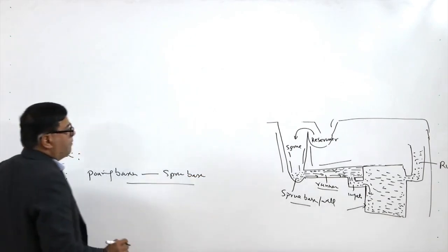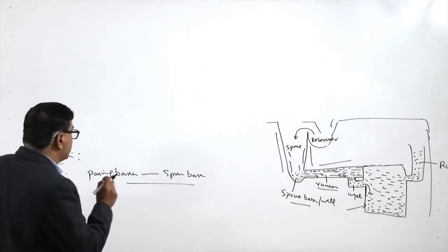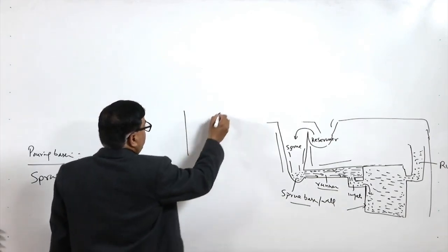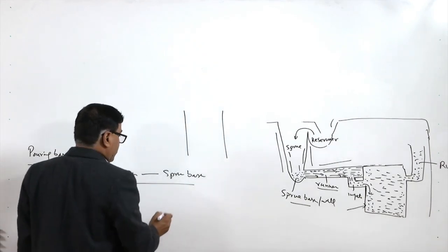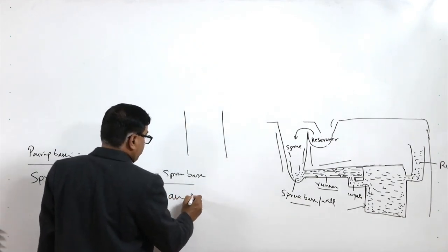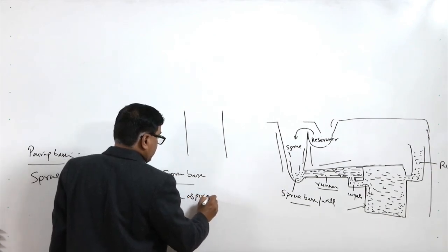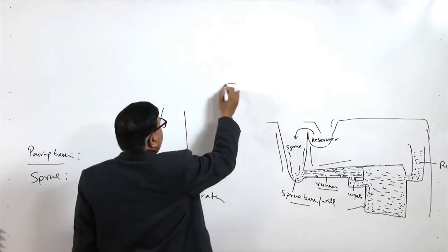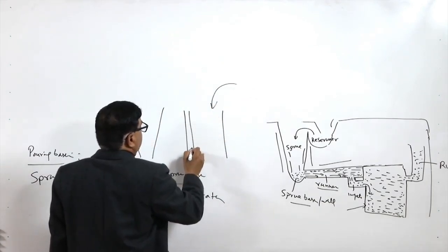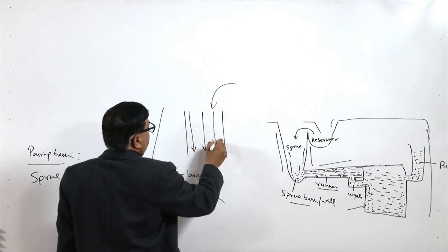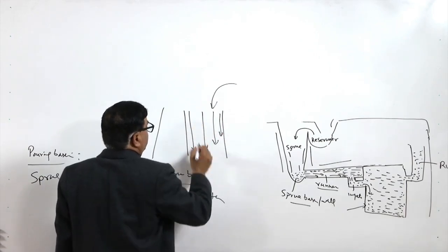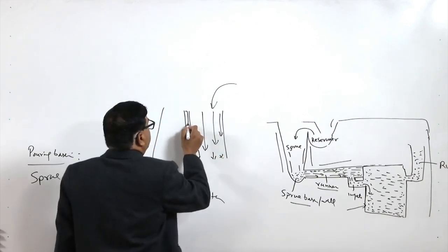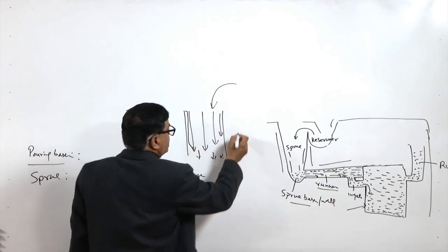A proper design of the sprue is needed, because a simple cylindrical sprue promotes air aspiration as compared to the tapered sprue. We know that if the molten metal is being fed from the top, with the change in position the velocity increases as the molten metal moves down, and because of this the separation of the molten metal from the walls starts.